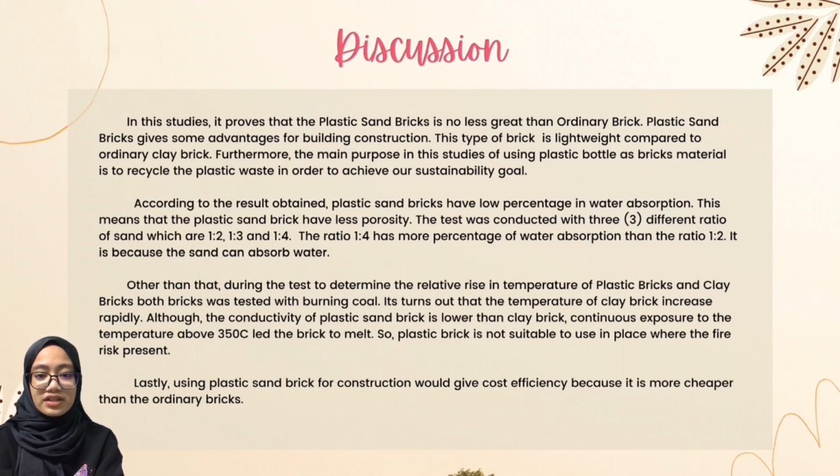It turned out that the temperature of clay bricks increased rapidly. Although the conductivity of plastic sand bricks is lower than the clay bricks, continuous exposure to high temperature above 350 degrees Celsius leads the bricks to melt. So, plastic bricks are not suitable to use in a place where fire risk is present.